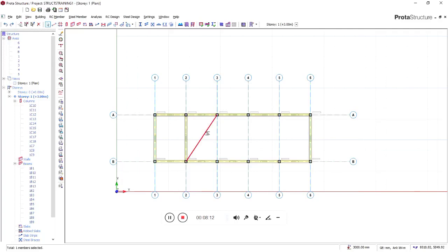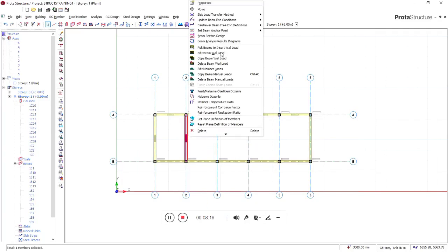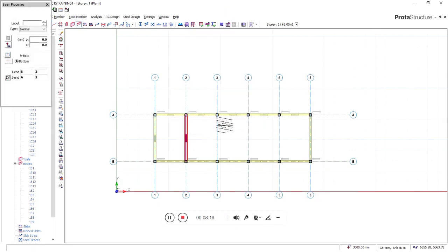What we should have done is, see, you click on it, select second point, and then you right click. If you press escape, it will take you back to where we're clicking on beam again, but when you right click, the member selection, the action you are doing presently, is still there.